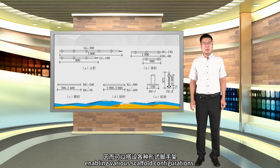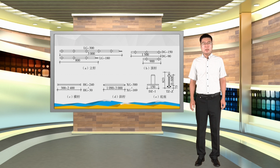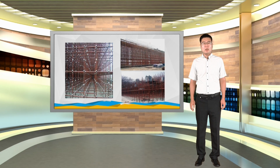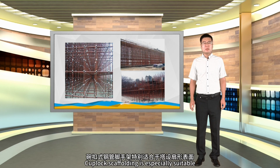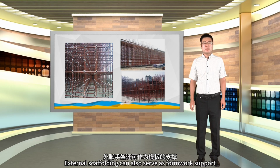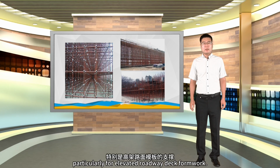enabling various scaffold configurations. When extending standards, the joints should be staggered at the uppermost lift, then leveled using 2 adjustable head jacks. Cuplock scaffolding is especially suitable for constructing fan-shaped surfaces and for dual-purpose use in high-rise building construction and decoration. External scaffolding can also serve as formwork support, particularly for elevated roadway deck formwork.